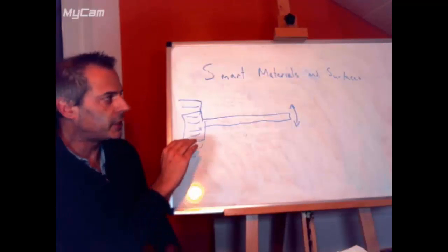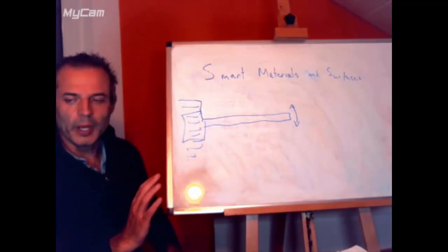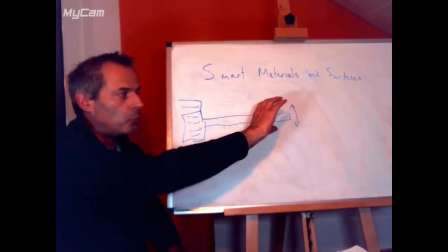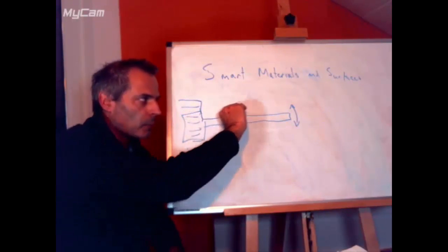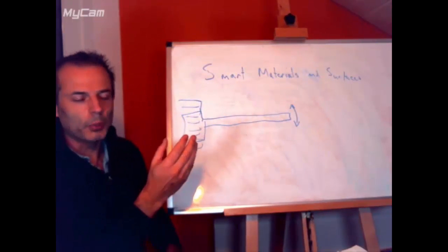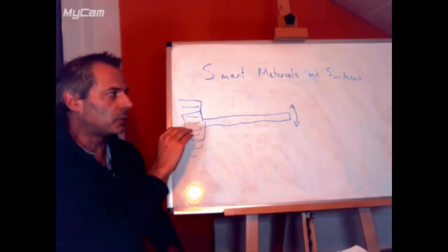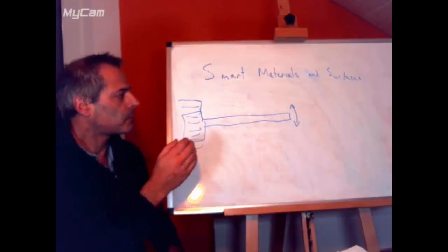If it's just one material, distributed all over it, then it will behave as if it's just the weight that is doing it. So if we make a perfect cantilever and we add material to it all over, then it will start to oscillate slower because it's heavier.